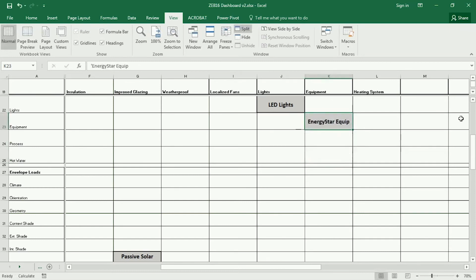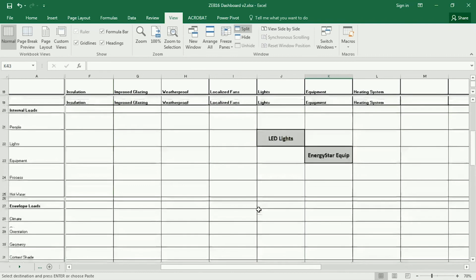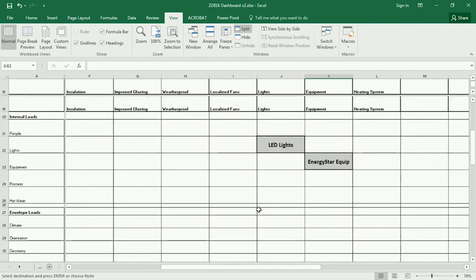And last one, for the heating system, I'm going to do a relatively large retrofit here and install heat pump radiators. So I'm going to dramatically improve my heating coefficient of performance that way. So these are the changes I'd like to make. In the next tutorial, I'll show you how fast and easy this can be to model quickly in EnergyPlus.